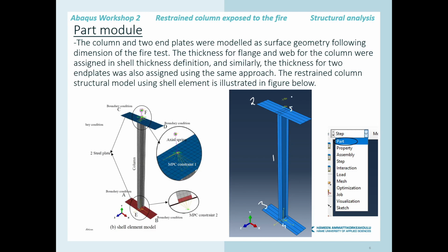The idea here is that it will be easy for the assembly, and then the idea is to start our reference global 0 0 point at the bottom point in the middle of the cross section of the column's lower end where the plate is connected.